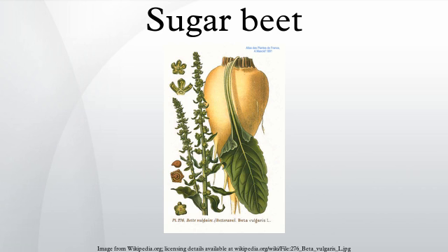The color of raw juice varies from black to a dark red depending on the amount of oxidation, which is itself dependent on diffuser design. The used cossettes, or pulp, exit the diffuser at about 95% moisture, but low sucrose content. Using screw presses, the wet pulp is then pressed down to 75% moisture. This recovers additional sucrose in the liquid pressed out of the pulp, and reduces the energy needed to dry the pulp. The pressed pulp is dried and sold as animal feed, while the liquid pressed out of the pulp is combined with the raw juice, or more often introduced in the diffuser at the appropriate point in the countercurrent process. The final byproduct, vinasse, is used as fertilizer or growth substrate for yeast cultures.